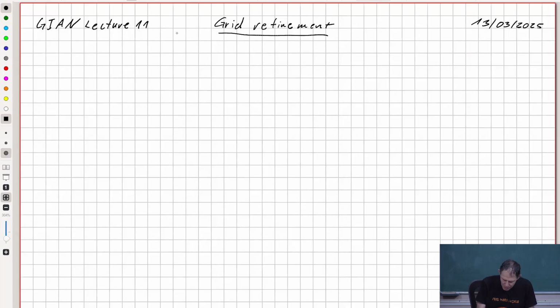And this is in particular a problem for external flows. So in internal flows, such like flow through pipes, engines or so on, you actually get along with a really Cartesian grid with constant resolution quite well.